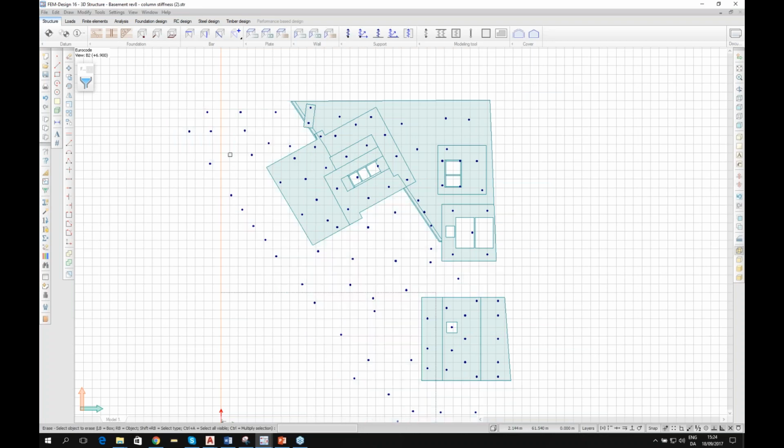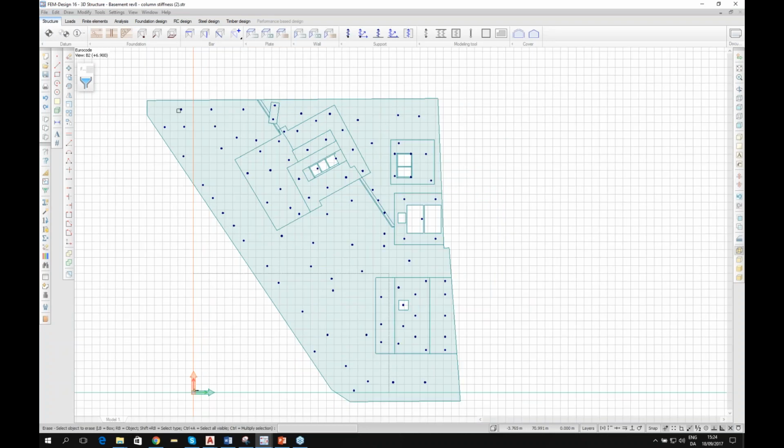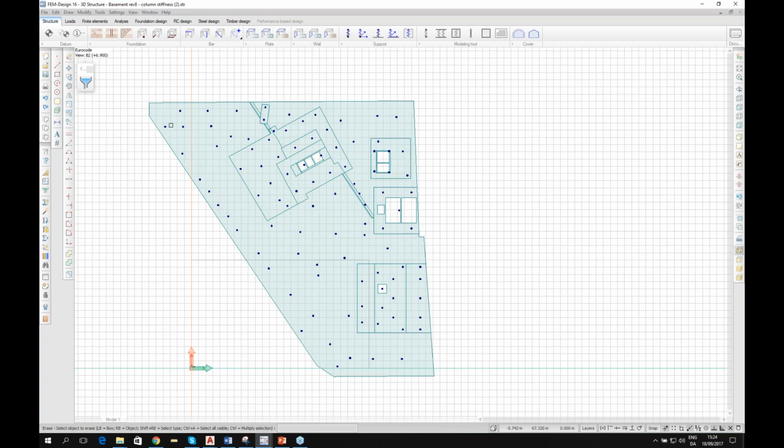I just click on it with the delete until it completely disappears. And if I undo it once, pressing Control Z, or there's also one undo here, I make sure that I have one surface drawn there. I make sure that there is no double or exactly overlapping surface on top of each other.